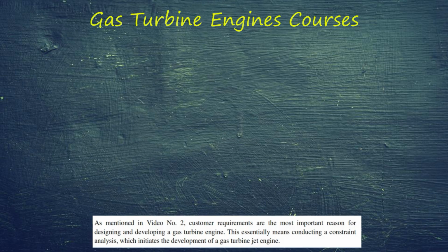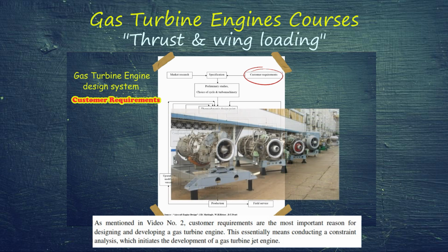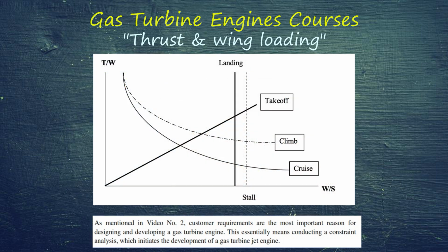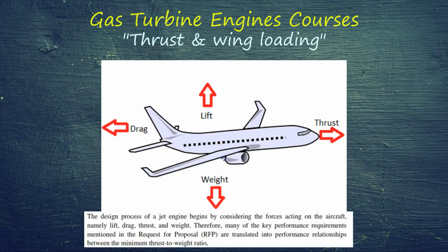As I mentioned in video number 2, customer requirements are the most important reason for designing and developing a gas turbine engine. This essentially means conducting a constraint analysis, which initiates the development of a gas turbine jet engine. The design process of a jet engine begins by considering the forces acting on the aircraft, namely lift, drag, thrust,